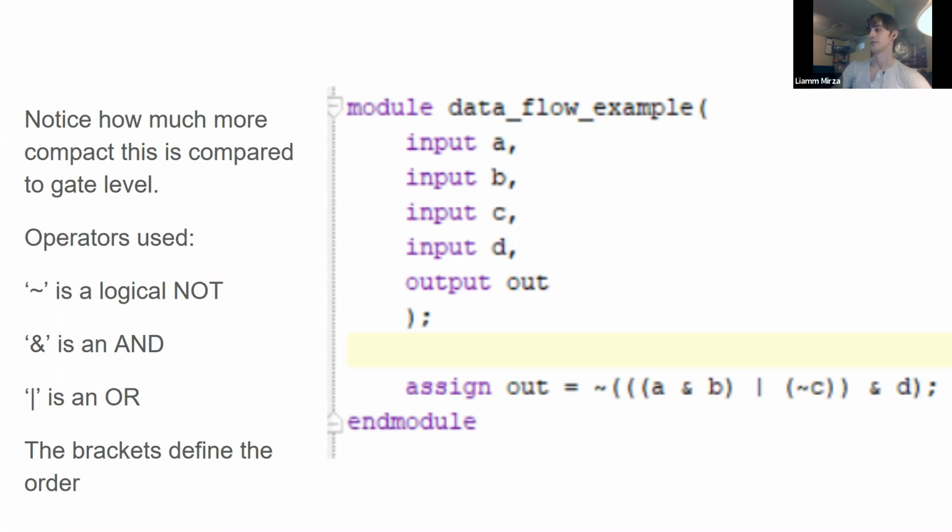And what we have here is the data flow model of our circuit, which is much, much more compact than the gate level one. I think you can really appreciate the data flow model here. Yep, I think it's the most compact one out of all. Though I sometimes see designers forgoing this one and just using only behavioral, but I think that's just out of habit. This one's still quite valid for design even nowadays.